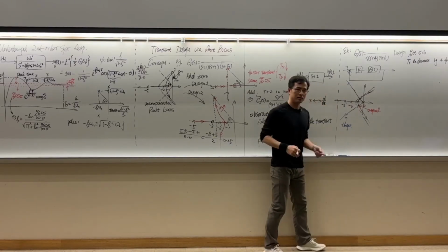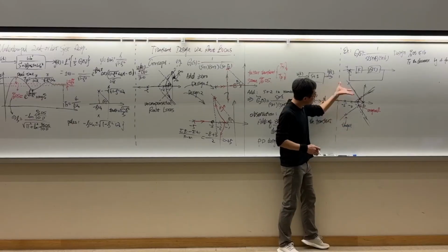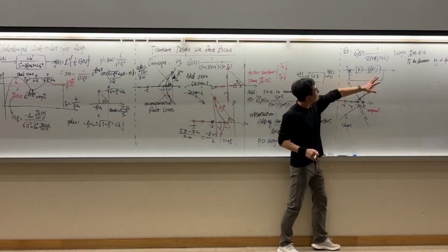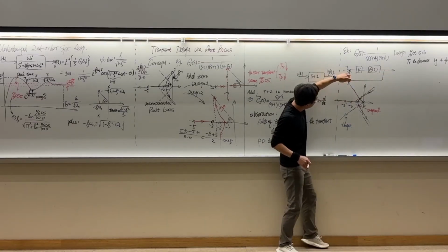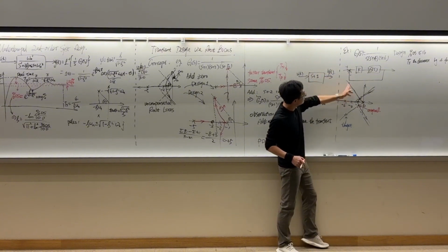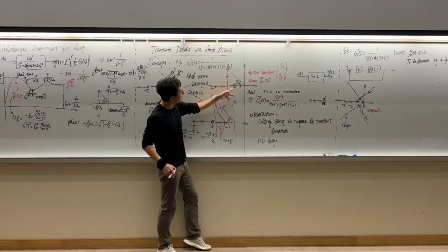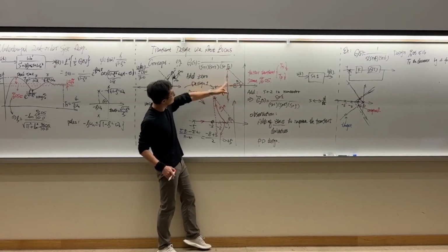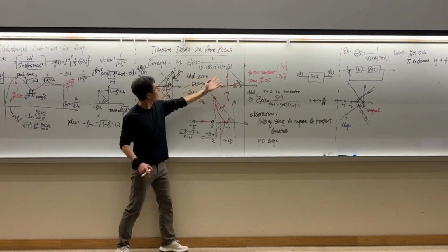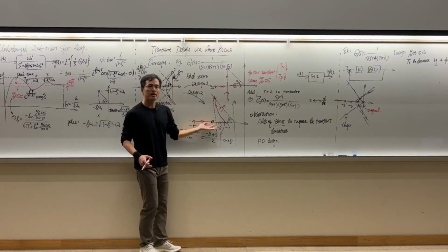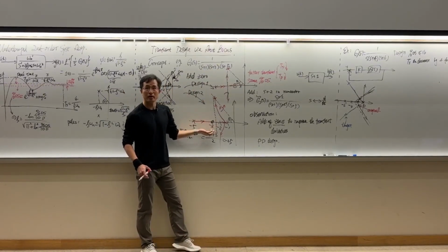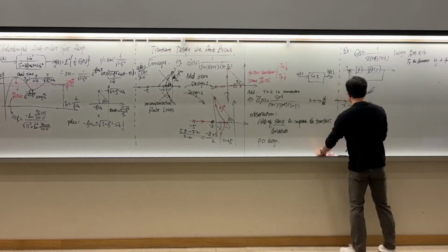So that's the design space we're going to have. We're going to need to come up with some closed-loop design to make the root locus go to here. So think about scenarios over here. We need to design the system such that the root locus will go to the left compared to this one. And adding zeros seems to be the way, right? So that's the general concept.